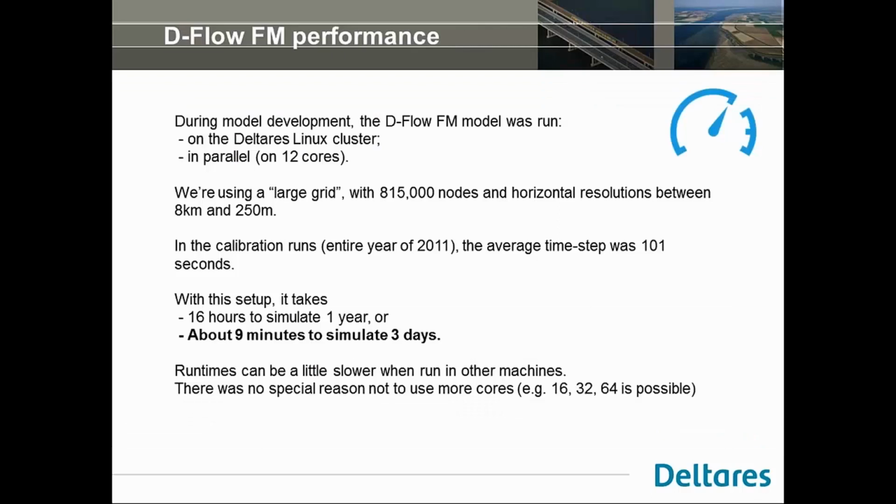A question that we get very often is, well, how fast does this all run? It's quite useful and important information, especially if you have operational simulations. Delft3D Flexible Mesh not only allows you to optimize the grid, but also allows you to run in several cores at the same time, what we call parallel computing. In this case, we did all our simulations over 12 cores in the Linux cluster we have at Deltares.